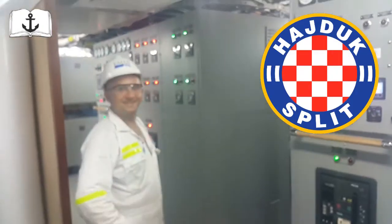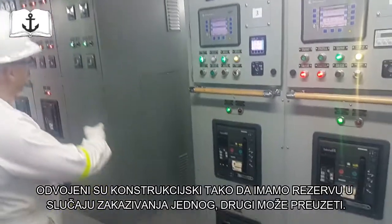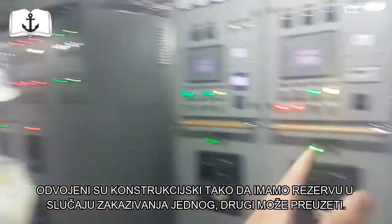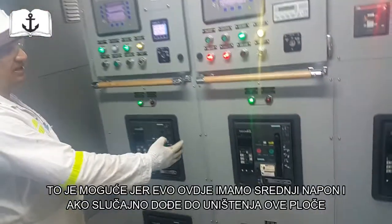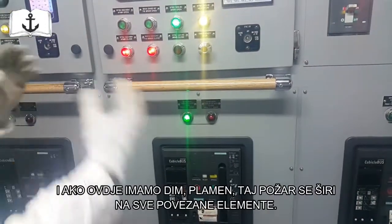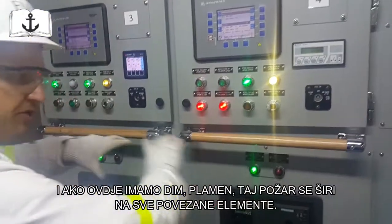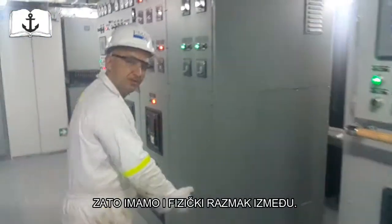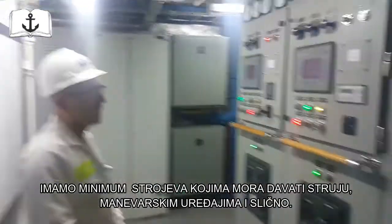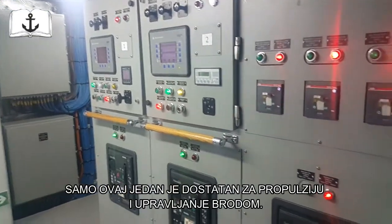So why are they separated? They are separated by construction so that we have redundancy. If one of them fails, the other one will keep working. That is important because we have medium voltage there, and there is a possibility of an explosion of this box, and then you have fire, smoke, and also current and arc. The arc will destroy everything on the bus bar. That's why you have the separation, so that one will keep working if the other fails. The minimum requirements are in the class, and you will have maneuverability and everything. So we will have propulsion and everything just on this one.